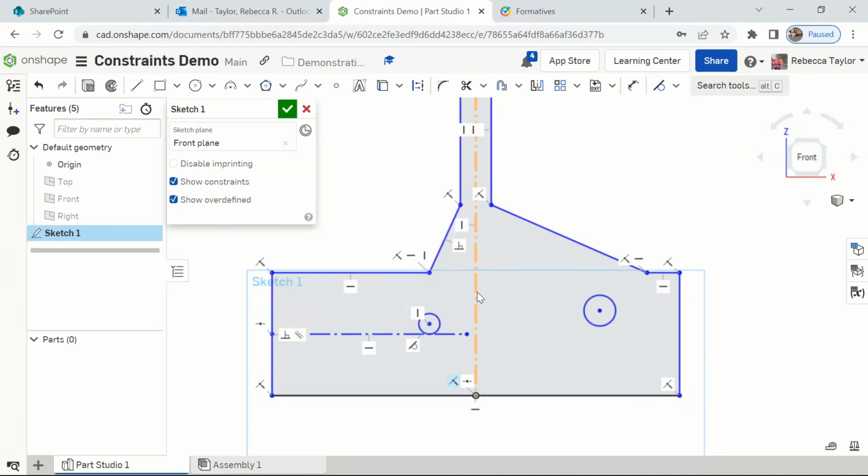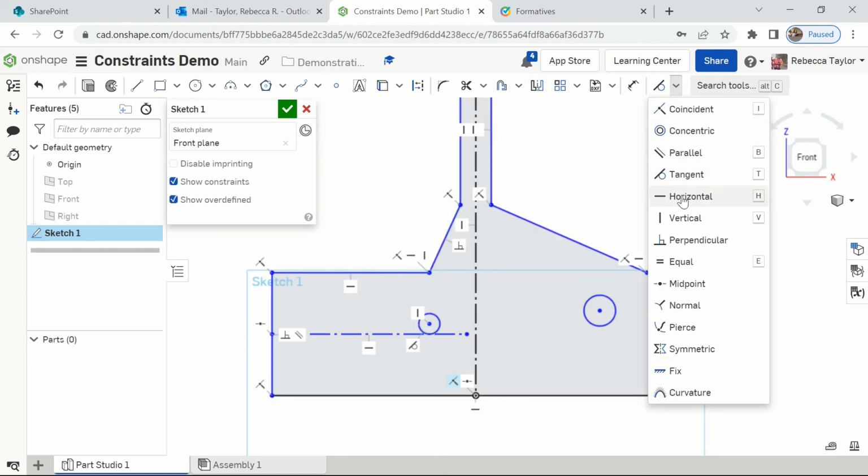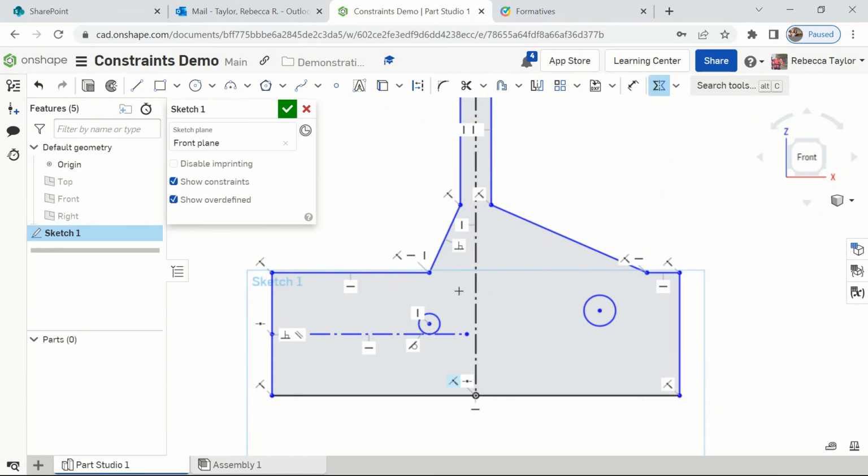I don't like this way of doing it. I think I prefer doing a mirror, like drawing it with the mirror option as opposed to putting a constraint on it, but it doesn't behave exactly the same way. So, okay, I'm going to take my first circle and my second circle and the line that we want it to be symmetric over.